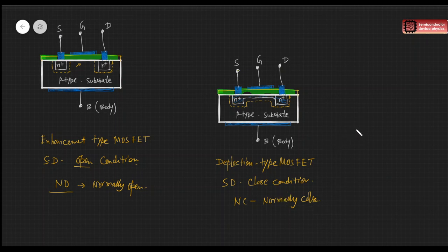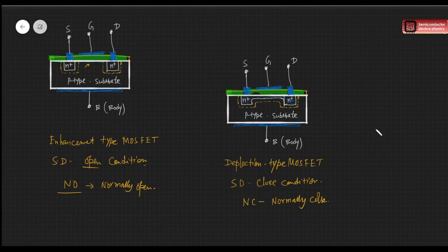If you take a relay, let's say it is a single pole double throw relay, SPDT. Usually you will have three terminals in the relay, right? One is common, the common port in the center, and then we'll have NO and NC.